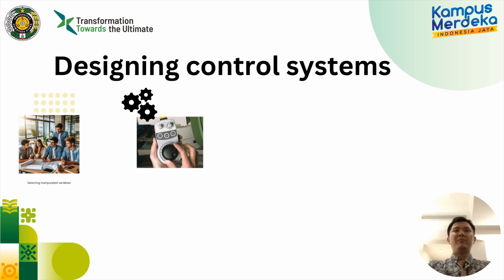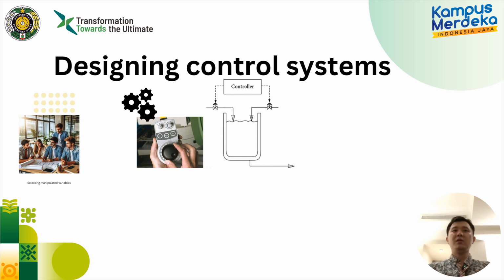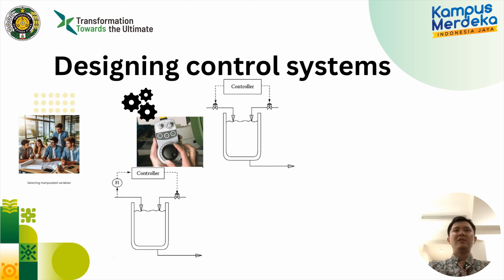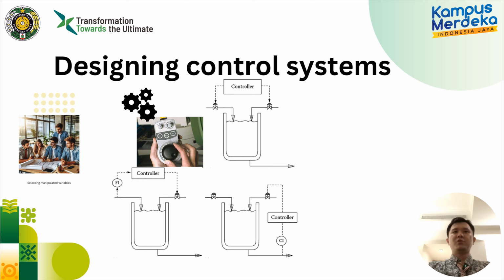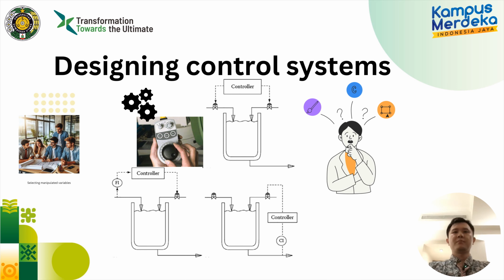If a human operator implements the control action, it is a manual control scheme. If the control mechanism acts without current information about the status of the process, it is an open-loop control scheme. If the control mechanism anticipates the effect of the disturbances, producing a corrective action, it is an anticipatory control action or a feed-forward control scheme. If the control mechanism acts using the information fed back from the measured outputs, it is a feedback control scheme. What is best for a given problem is a critical question for the quality of the control system and is problem specific.